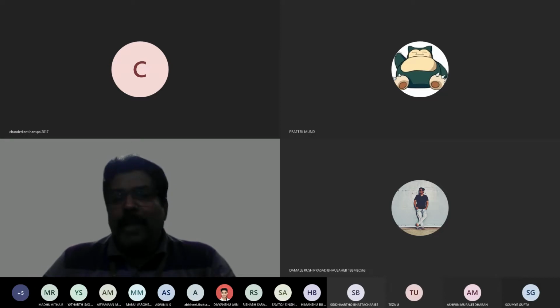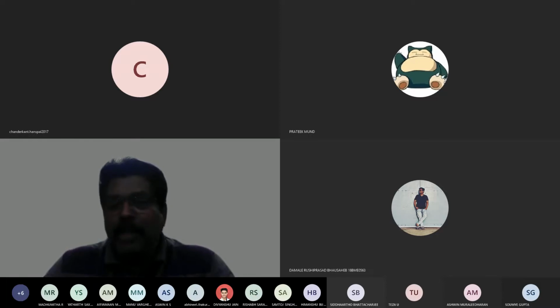So what we have done in that is, we have looked at a tire not as an elastic tread band, what was considered in Julien's model. Instead, Temple and Von Schlippe proposed the tire to be a stretched string model, wherein we define an equatorial line, and that equatorial line's deformation for the side force is what we considered, and its physics is what we looked at.